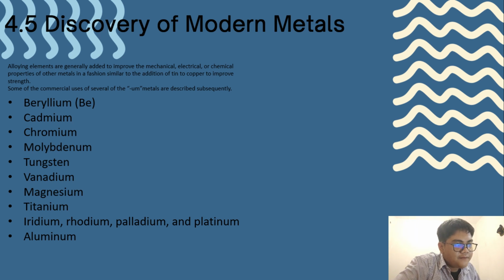The major use of tungsten today is in the form of tungsten carbide, which is a very hard, wear-resistant material. Carbide tips, drills, and machine tool inserts account for 65 to 70% of all tungsten use and are found throughout the home and industry. It is interesting to note that tungsten, which is a very brittle, high-strength material at room temperature, can be fabricated into the fine wires required for light bulbs.